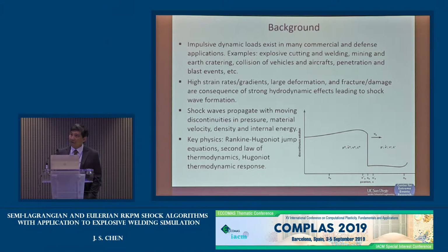And the shock front, the shock speed, is a very important quantity that, when we do computation, has to be very accurate. Otherwise, you miss a lot of important physics in the problem. And the key mechanics in these problems are the Rankine-Hugoniot jump conditions, the second law of thermodynamics, and the Hugoniot response.